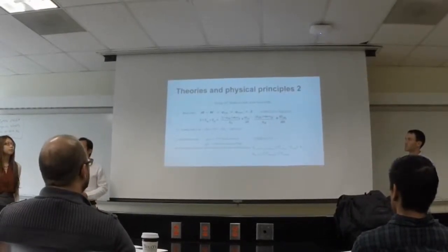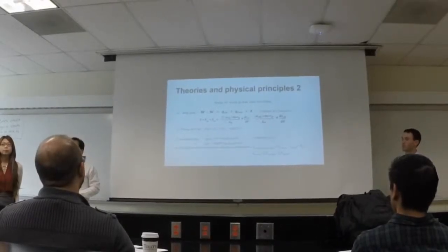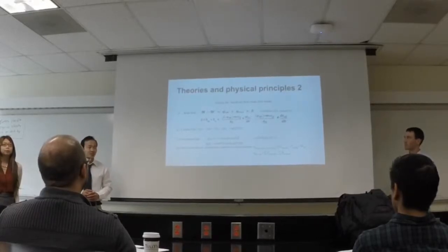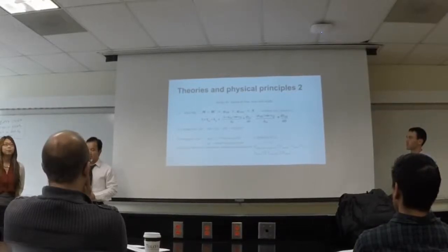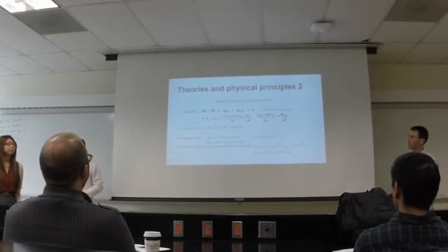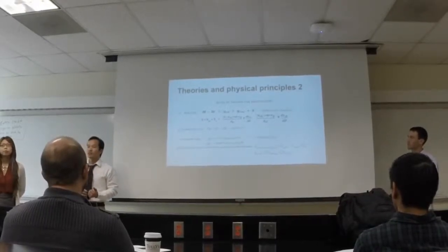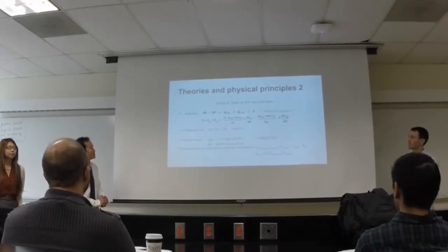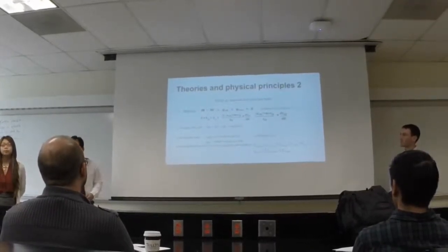And talking about the theory of how to design the AC unit, there are four main heat loads we need to take into account. The first one is the body heat coming from the person inside the tent. The second one is to cool the air inside the tent. The third one is the ventilation loss. And the last one is the cooling loss from convection, conduction, and radiation. There are some simplified equations for each type of cooling loss.